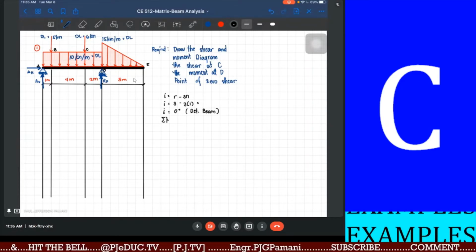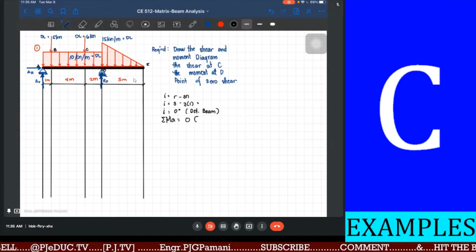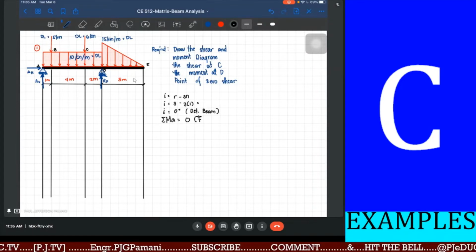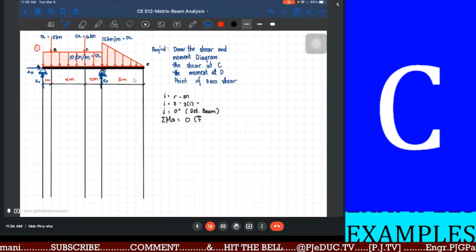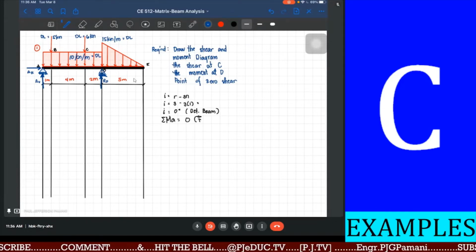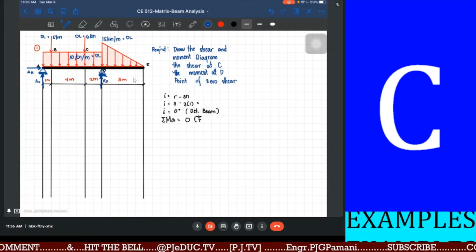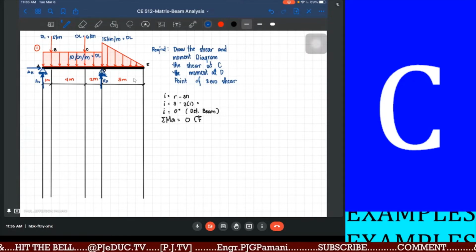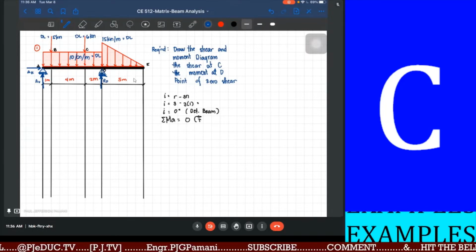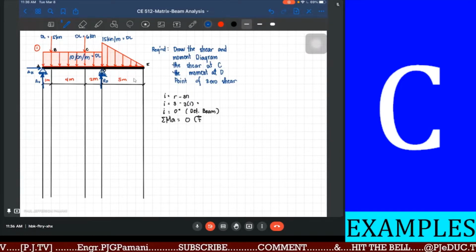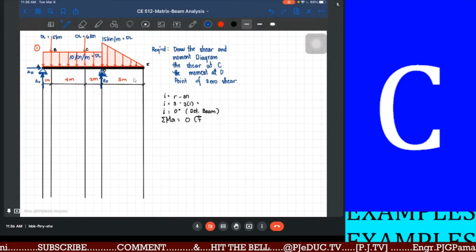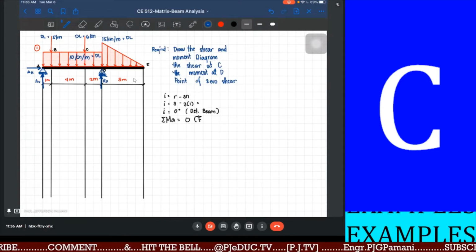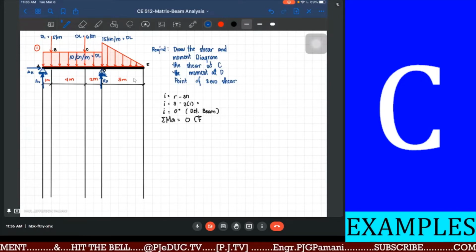Summation moment at point A equal to 0, clockwise forces positive or resulting forces positive. Okay? Unahin muna natin yung concentrated kasi yun yung pinakamadali at saka yung ating reaction at point D. Okay? How far does the concentrated load of 5 kilonewton is at point A? So, gaano siya kalayo? 1 meter. Moving clockwise, counterclockwise.